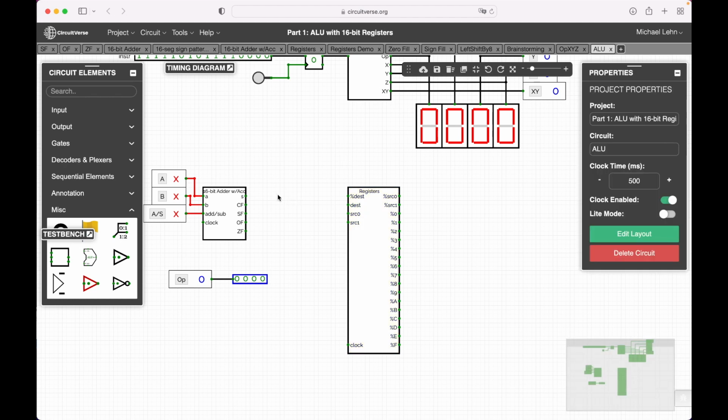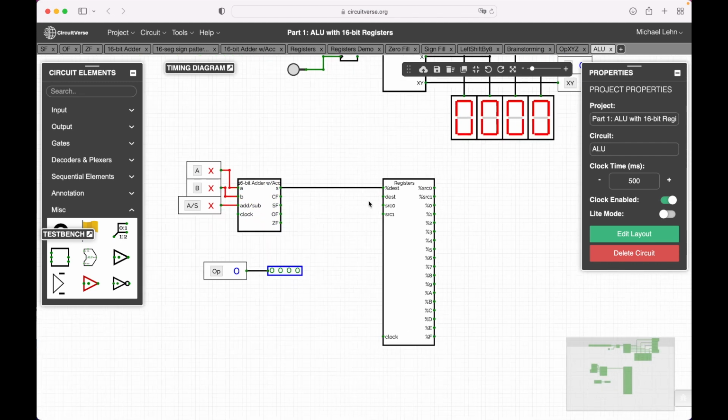You will also see that this sum that gets computed always can be connected here with the bit pattern for the destination register. So because all operations I will map to a result of adding or subtracting something. But what might be different from instruction to instruction is the ID of the destination register, and of course also what kind of sources, what kind of register do I want to pick up here.